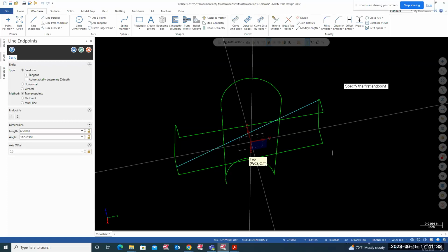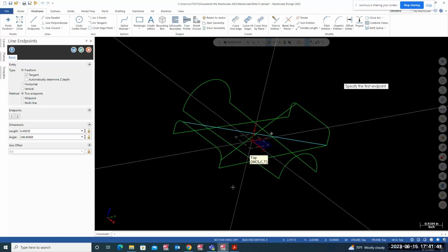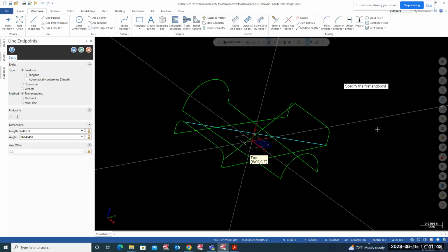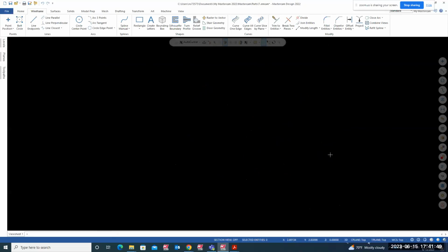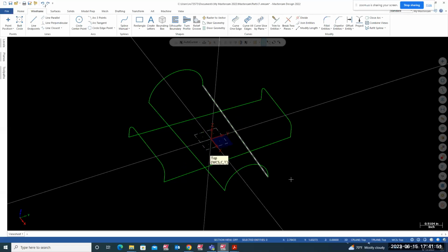I want to create a line from here. I want to go up to this point right here. Okay, perfect, not a problem. But you have to be in 3D. Can we do that in 2D? No way, because your Z controls. If I say undo, undo, now I'll go to 2D. The way you switch from 2D to 3D, guys, is just left click on your mouse. Left click on your mouse, change to 2D, left click on your mouse, change to 3D.